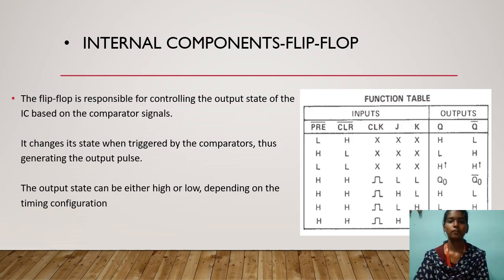Internal components of flip-flop. Here you can see the function table of inputs and outputs. The flip-flop is responsible for controlling the output state of the IC based on the comparator signals. It changes its state when triggered by the comparators, thus generating the output pulse. The output state can be either high or low depending on the timing configuration.